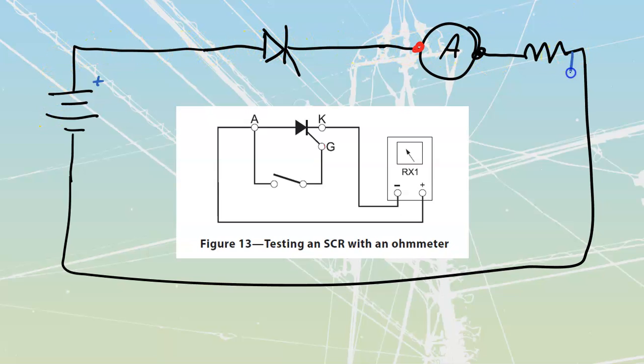Generally speaking, if you get into industrial electronics in particular, you should have a couple of fairly high wattage rheostats, variable resistors, that are going to be with you so that you can actually do this testing on the fly. Once you establish that current, so you do that tap, turn this thing on, you've got current through there, what you can do is increase your resistance. As you increase your resistance, bring it across this thing. Sorry, wrong direction. I would have to bring it this direction.